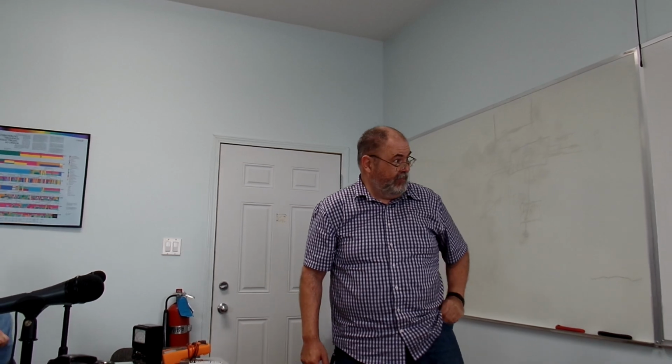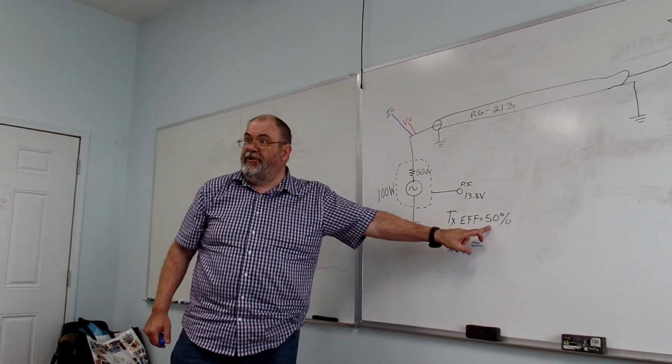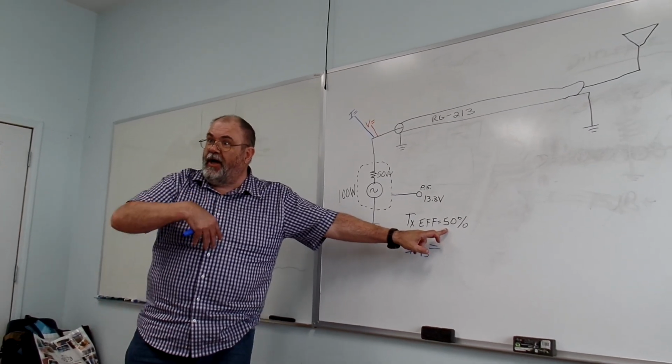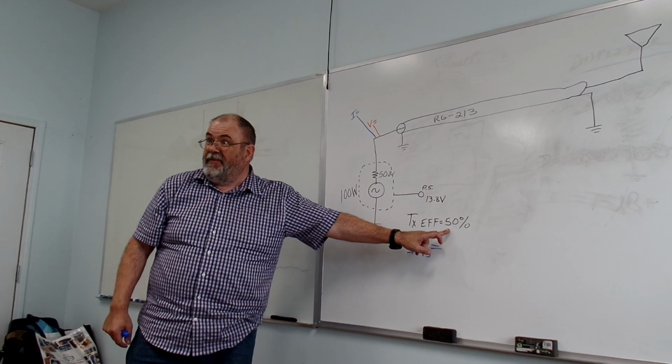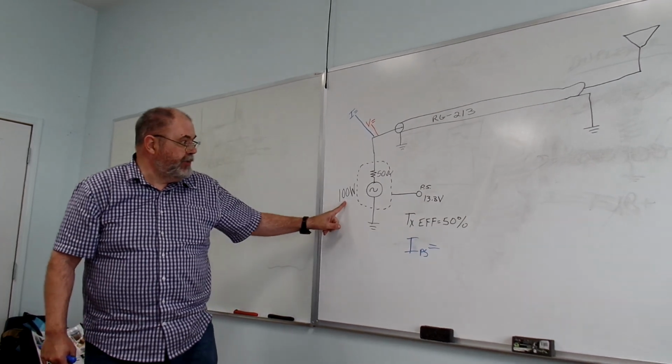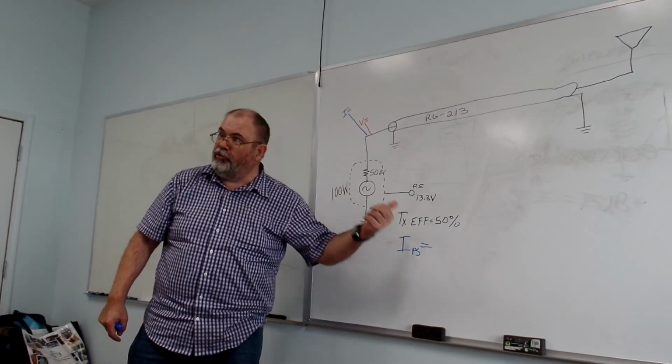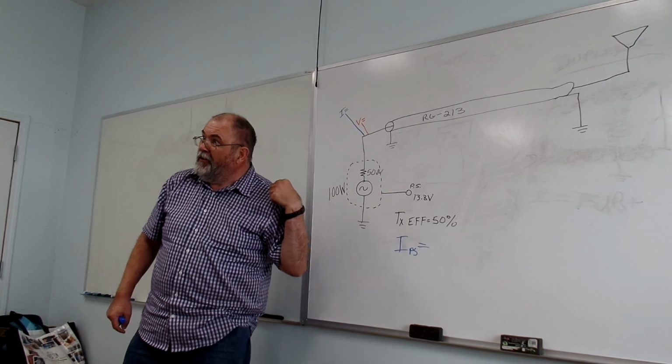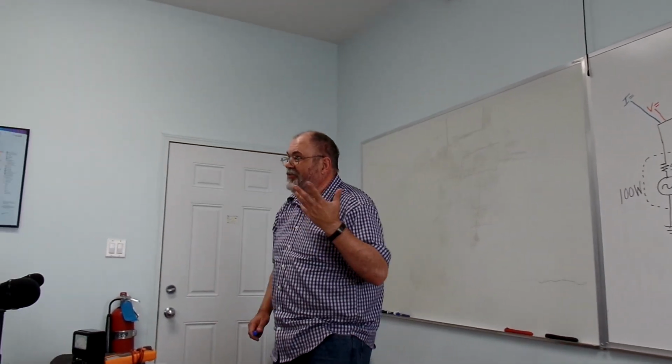7.2 amps. Yeah, but you have to double this because of the 50%. That's right, 50% efficiency, you need to double. The transmitter is only 50% efficient, which means half the power you put in is gone. So you have 100 watts, and 50 left. If you want this thing to put out 100 watts, you have to put 200 watts in. Right? Oh. So 14.5?